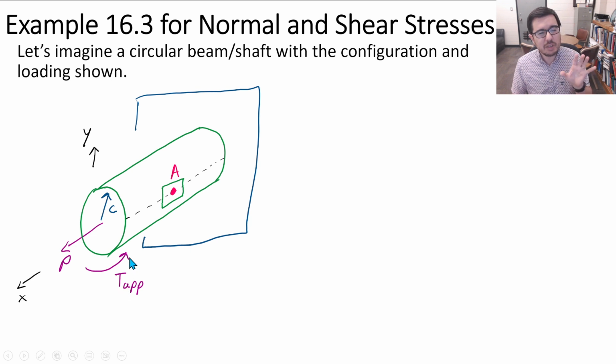The way I like to do it is I like to think of what is happening to the structure, what is happening to the beam as it's being twisted. And if you can visualize, like we've done before, when we had all these lines or this grid and how it's deforming, we see that this side is going to go up relative to the side that's farther away, and this side is going to be going the other direction.